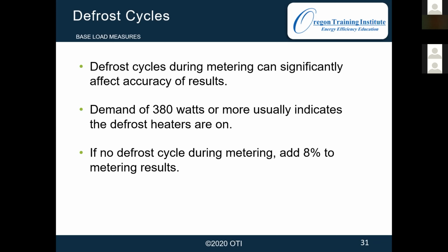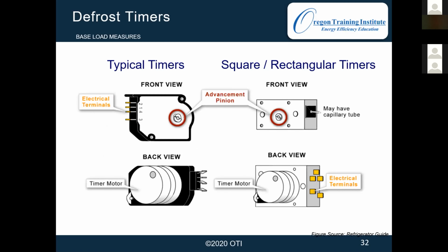And the defrost cycle on these older fridges comes in a couple different varieties of controls. They're going to be in the fridge, and they're essentially timers. They're going to control when it cycles. So on here, see where it's circled in red where the little pin is, and that's going to rotate. And we can turn that to advance the cycle, and we can kick it into defrost and then out of defrost, so we know we're starting at the beginning of the cycle and we're not going to go into defrost during our 2 hours.